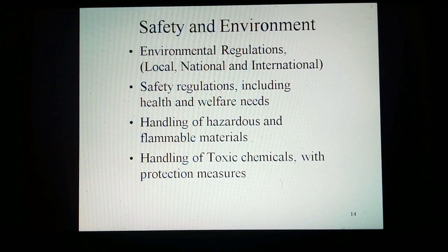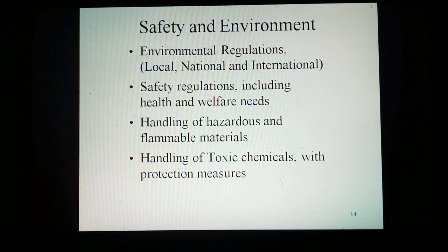If the process fluids are especially toxic, layout is affected by the need for closed chemical sewers and other protection measures. Security requirements may require special layout design when the plant produces a high-value product. If the plant site is governed by particular building, piping, plumbing, electrical and other codes, these can affect plant layout. Similar governing standards and regulations in the plant site affect the layout concept.